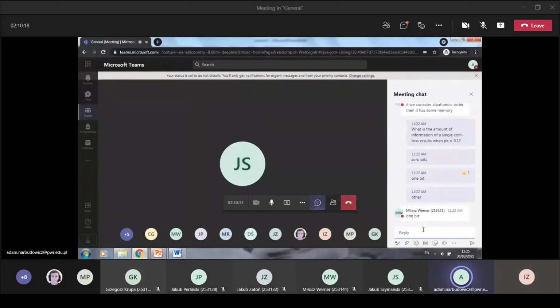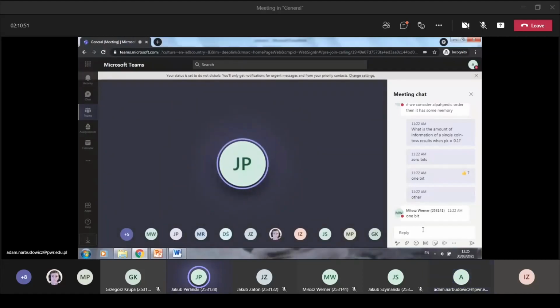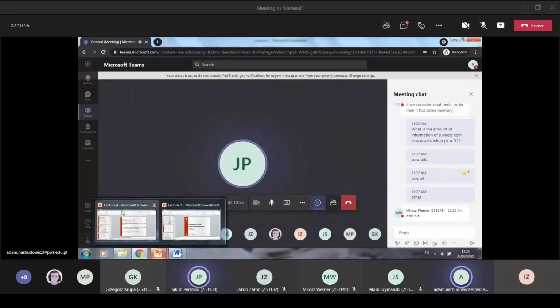So again, when you are transforming an analog signal into a digital form, what is typically the first step you should do, based on what you just saw in the slide? Sampling or filtering, maybe? Yes. So which one of the two? I guess it would be better to sample it after we filter it. Yes, exactly. And the next question that follows is why?